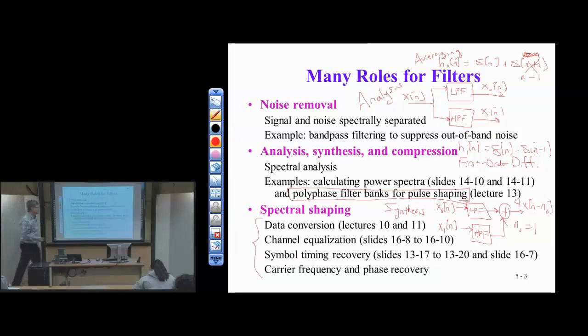In terms of compression, what can happen is if we can break up the signal into these frequency bands, then we can assign a different number of bits for each band based on their relevance to how they'll be used. So if we're going to view an image or hear audio, then we put as many bits into each bin as our human system would respond to that band of frequency. So in audio, for example, we have a sweet spot right around 1 kilohertz.